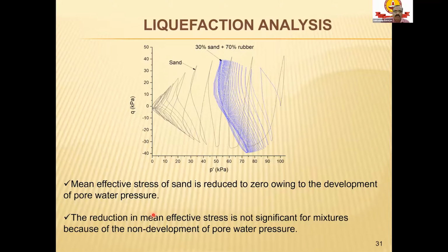Now, people may ask, what about the liquefaction problem of this kind of material? Because it's a very small, tiny size, and if it is saturated, definitely there is a liquefaction hazard. So we used a relatively loose sand, I think less than 40% relative density, and applied the same level of CSR in stress controlled liquefaction cyclic triaxial testing, and we saw that the sand liquefies quite easily, I remember hardly 40 cycles, less than that.